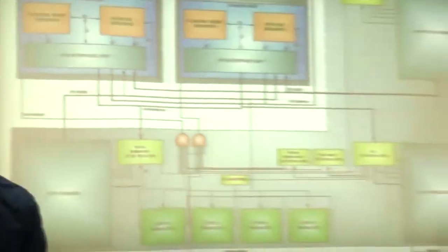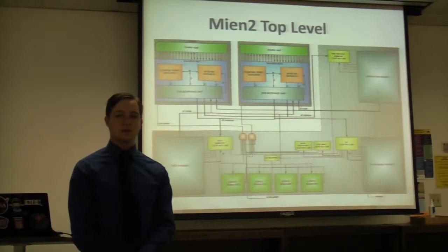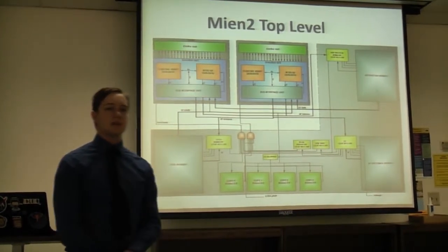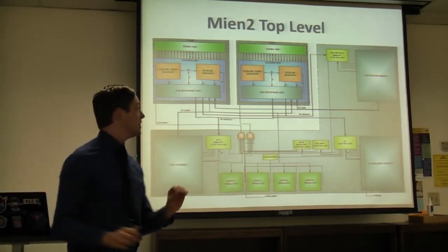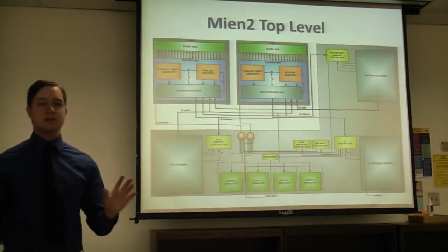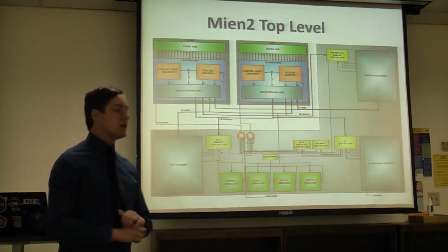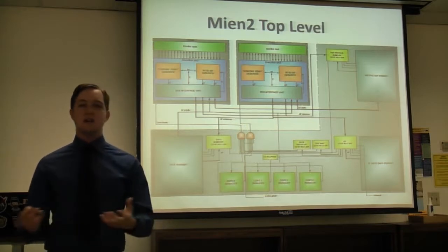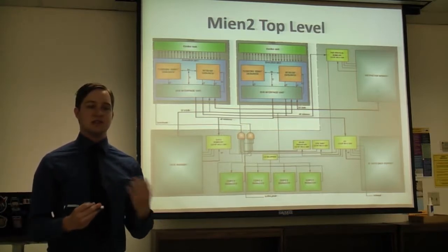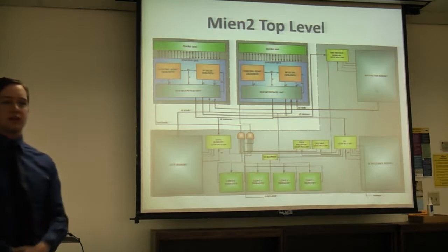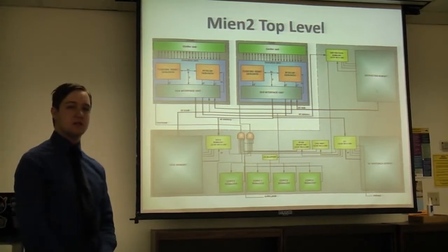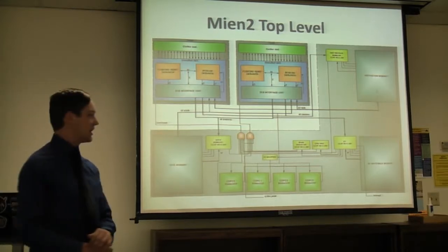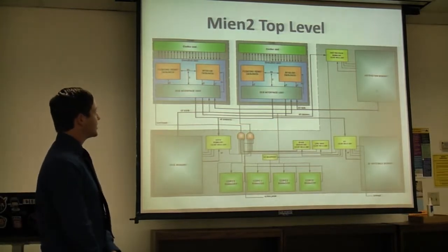What happens if there's a jump or a call instruction? How do both your cores handle that in terms of IP? They have different IPs. They're not running the same program. The CPU itself is duplicated twice. One of the main features of the way we implemented this is that we can take in almost any core with a slight modification to it and run it as a dual core in our system. Any core running the baseline ISA as specified by this project.